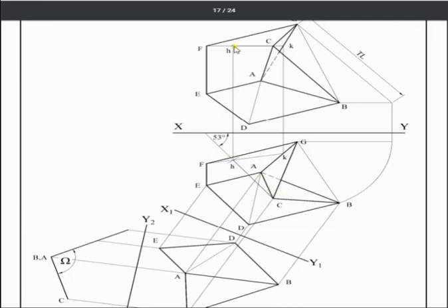So we can find H here, so that's the line now drawn in our elevation, and then all they're asking is for the true angle for this horizontal line and the vertical plane. And remember, the vertical plane is this XY line here. Imagine it's the back wall rising straight up from the XY line here.